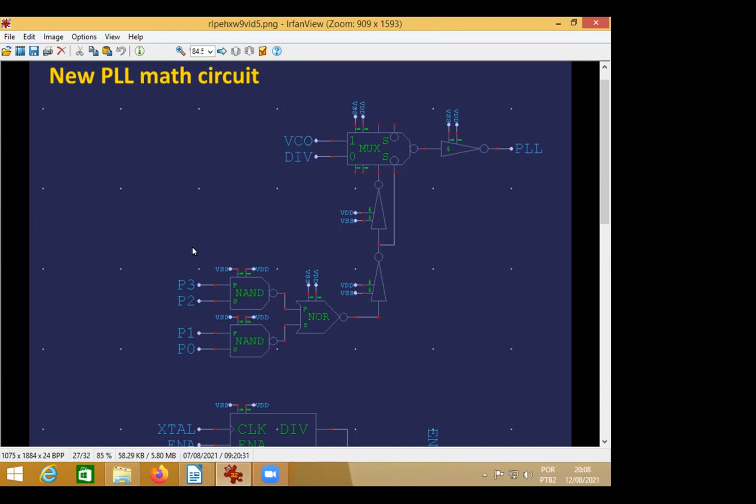So the other branch of the ORs will keep the output 1 for just some more clocks. And when we cut the DIV signal, it will just be the VCO changing. There will be no glitch because it's like using wired OR configurations.